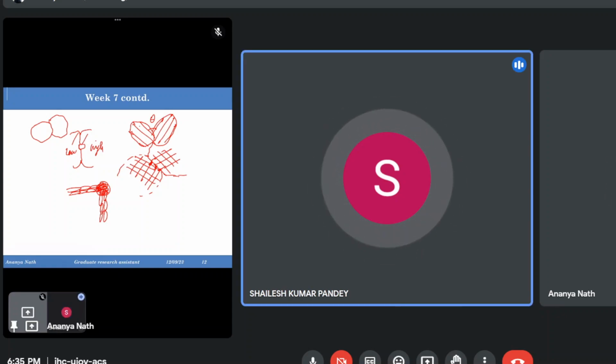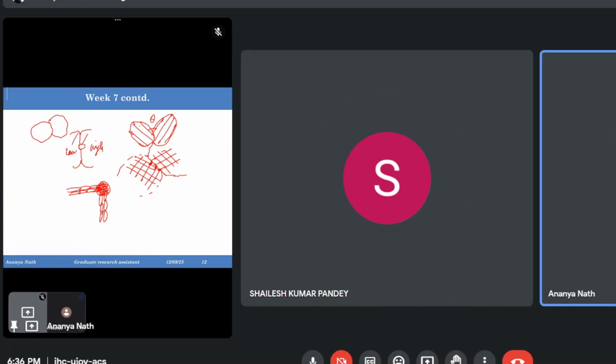Actually, why this doubt has arisen: we are saying these are low angle configurations of dislocations, and again if they interact, they make high angle boundaries between them. So if it is a high angle boundary, it cannot be equiaxial, because a high angle boundary means there is a high energy zone between them. There is a lot of mismatch between their orientations. High angle means that, right?